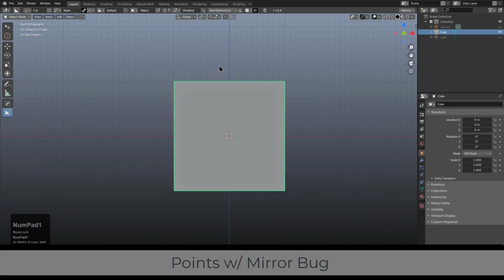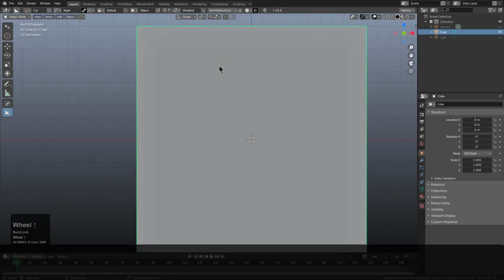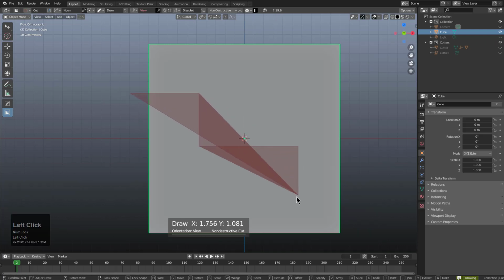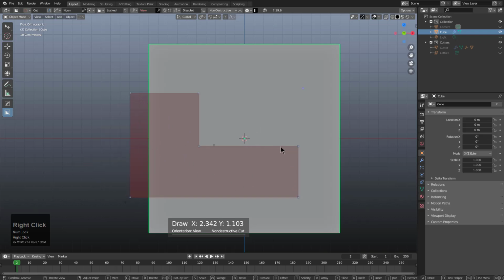Another improvement that was had with Ngon points is this relationship with the mirror. So here we are using the previous version of Boxcutter 719.6, and I'm just going to draw a simple shape. And once we have this in a pause state, I can press 1 in order to activate mirror. However, I can also press Shift 1 in order to flip which side is mirrored.